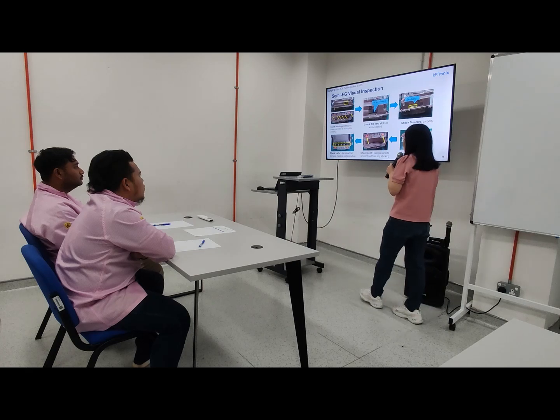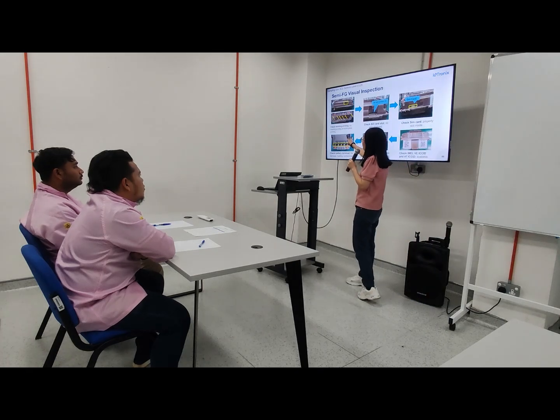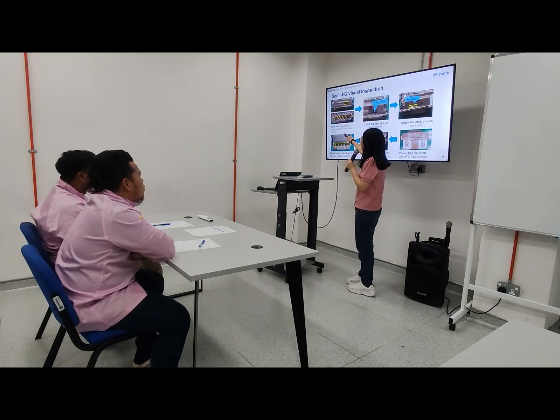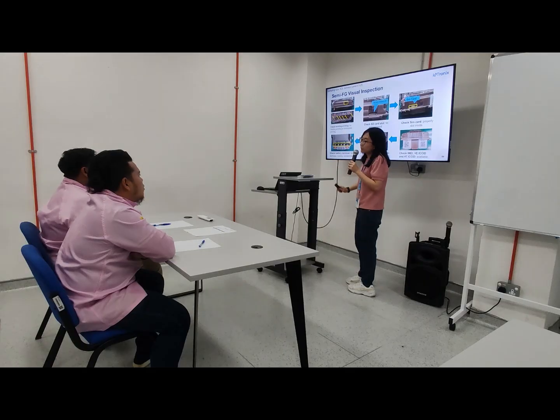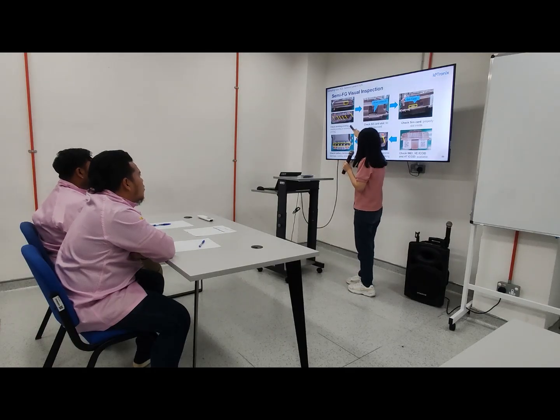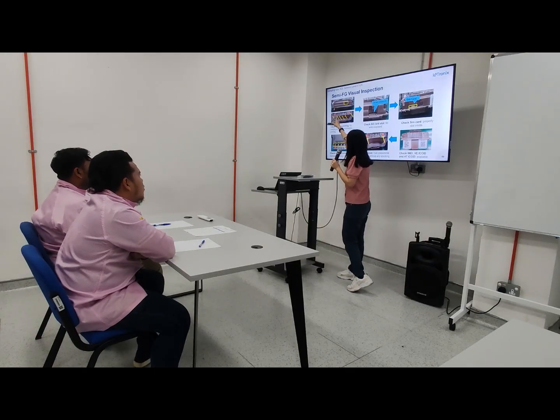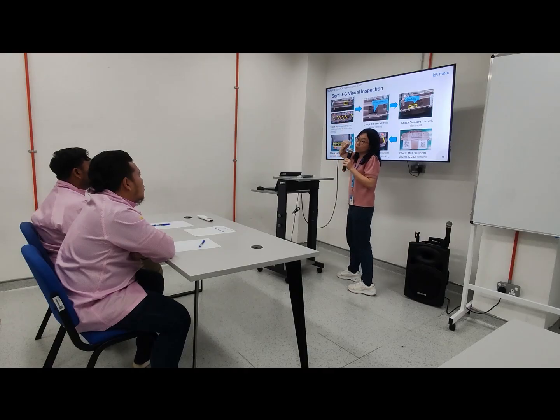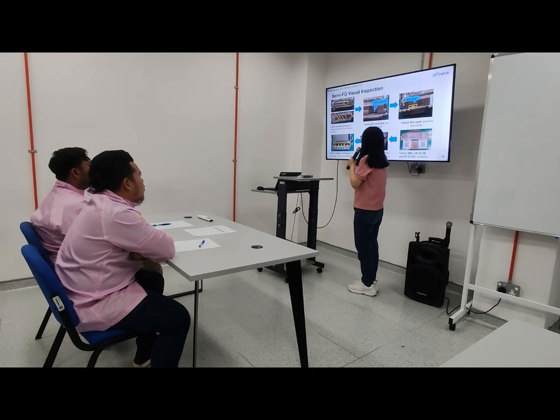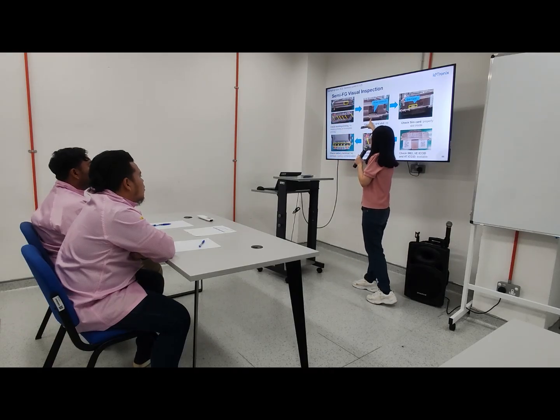Okay, next we will go for wording printing checking. Check whether any misprinting or incomplete printing for all the wording, all the symbols. Okay. Next we will check the SD card slot.